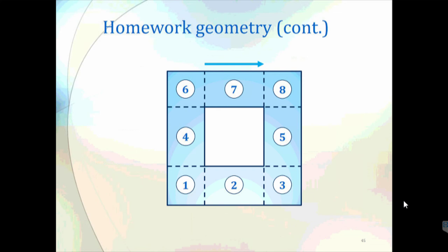Now, in order to import this block into OpenFOAM, we have to create blocks of our own in OpenFOAM. And each of those blocks has to have a portion with fluid. We cannot have a block where there is no fluid or no flow taking place.